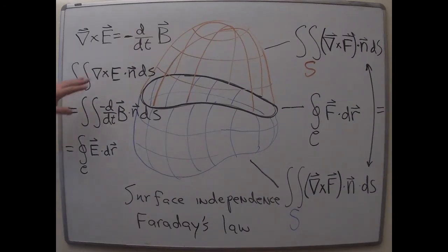And this is actually the fundamental principle that makes transformers work. A varying magnetic field creates a curled electric field. When a field is curled, you can pull energy out of it. When a field has no curl, then it's conservative. So this is where the conservatism of an electric field goes away in the presence of a changing magnetic field. You get this often really bizarre behavior.